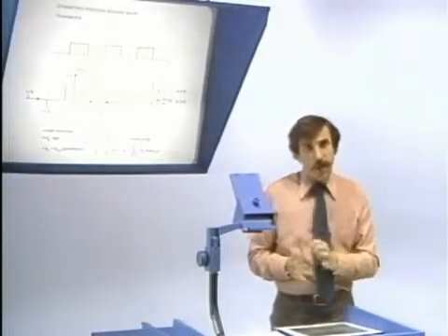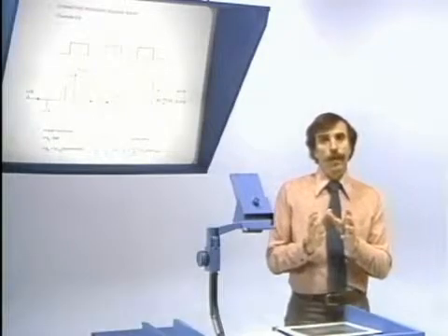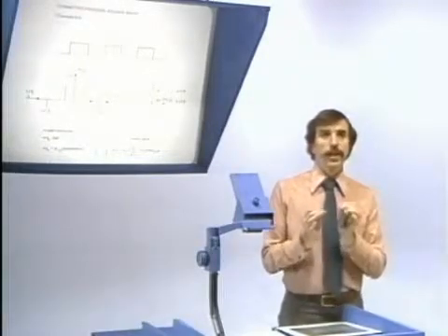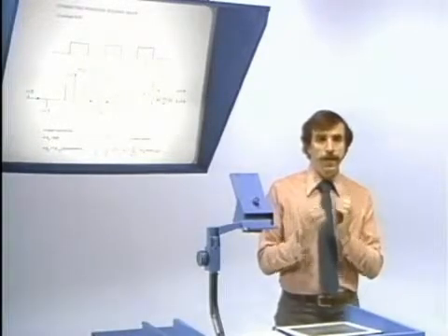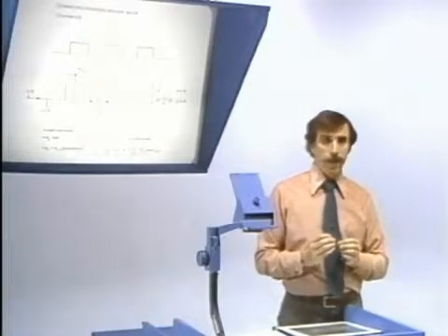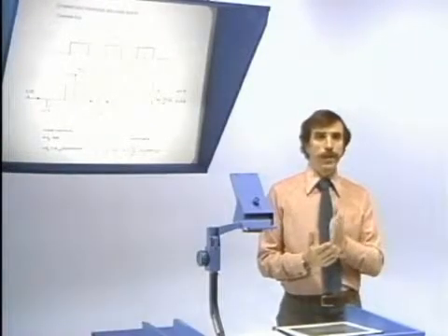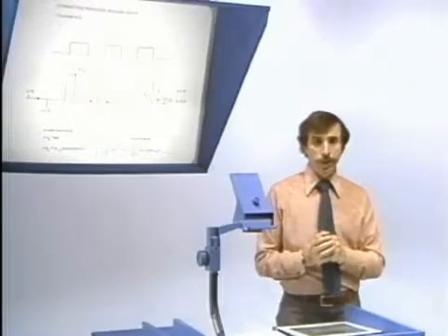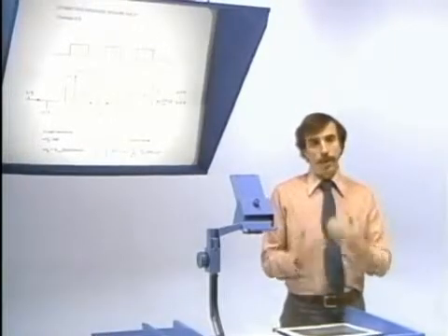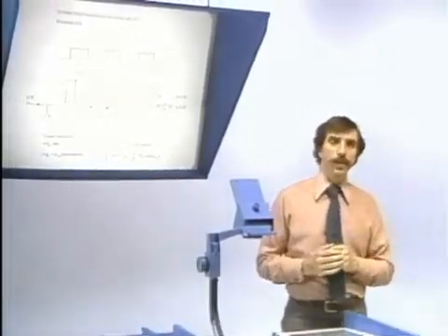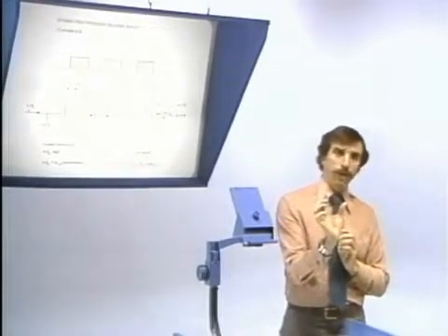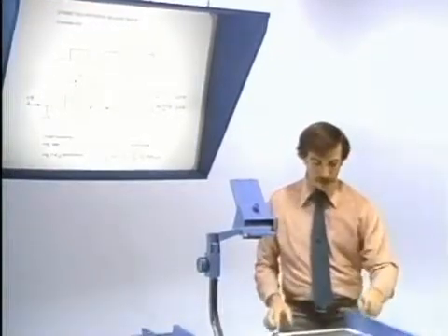Furthermore, in the two examples I've shown here, in both cases, the signal is odd harmonic. In other words, for even values of k, the coefficients are equal to 0. Although I won't justify that here, that's a consequence of the fact that the symmetry is exactly about half a period. And if you made the on time of the square wave different in relation to the off time, then that property would also disappear.